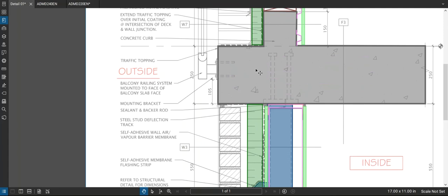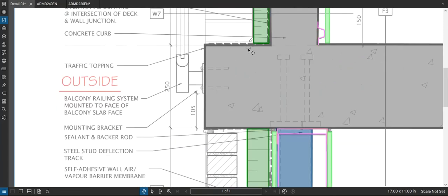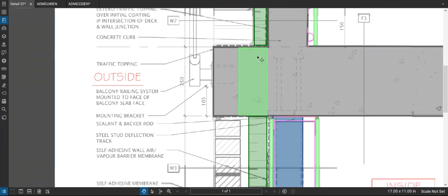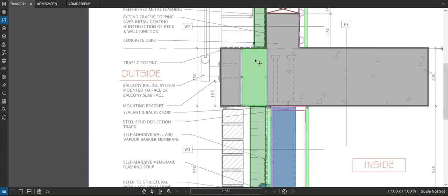Now back to what we really have. We don't really have a balcony there. So, if you were to put in that balcony thermal break product, you'd be left with just a bit of concrete on the outside, so the rebars would be sticking out. So that probably wouldn't work. However, you could probably cut the rebars off and just support that. But this is already a hint to how we can solve this in a better way right here.